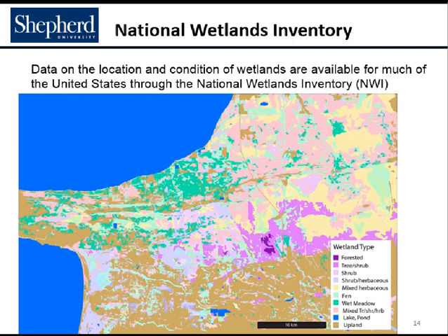Wetlands are categorized as a part of a lacustrine, palustrine, or riverine system. Lacustrine means lake, palustrine means pond. Subsystem designators then further specify attributes to record if the wetland is perennial, intermittent, littoral, or deep water.